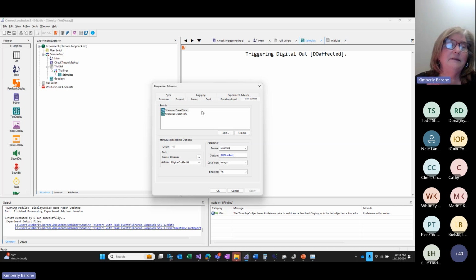Now, again, in this case, if you have the aux.io cable, you can only send 2 different values. You can only send 2 different triggers. Well, actually, you could send 3 because you could set both bit 14 and bit 15 high. But if you wanted to send both of those high, then you couldn't use the bit specific methods because the bit specific methods are bit specific. They're only turning on an individual bit on or off.